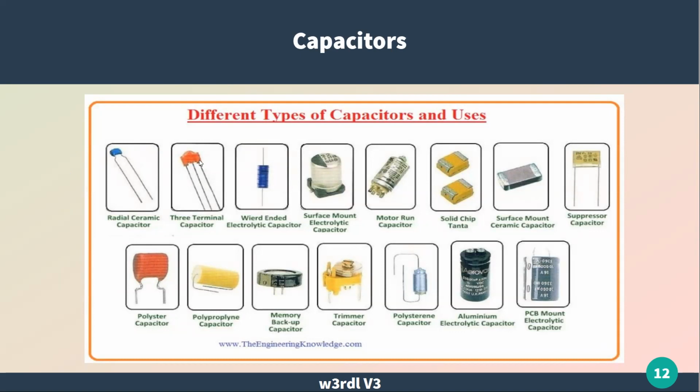This is a picture of all kinds of capacitors, the kind you typically would see. These are ceramics. Can't say I've ever seen too many of these 3-terminal ones. Sometimes you'll see axial leads, usually on an electrolytic, which is slightly different in that instead of just a straight dielectric insulator, it has an electrolyte compound like you find in some of your batteries. And it will allow it to store a lot more charge than you would with a straight dielectric. You can get these in very small surface mount packages.